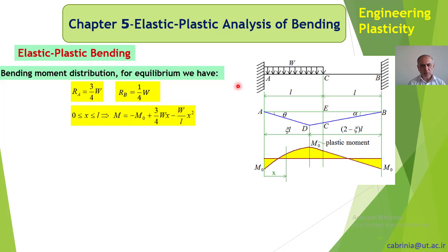Here again, we divide W by L, because we are considering at point X, so that we get the load per unit length. Then times X, we get W over L times X, which becomes the load up to point X, and then we want the moment, so we multiply by X, so that's what we get.